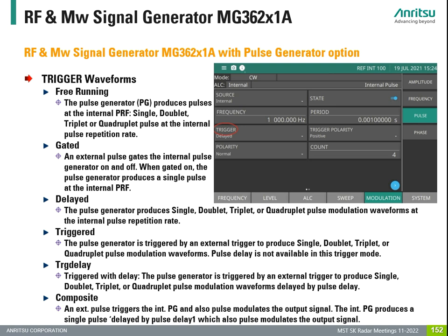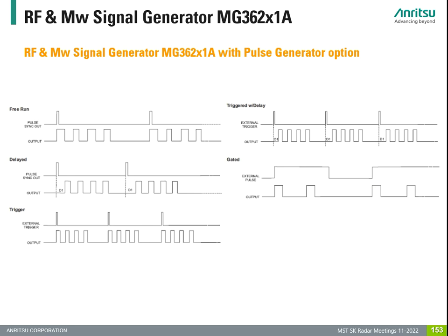For sure, it is possible to apply trigger to waveforms. Standard operations like free running trigger, but also gated, a delayed or an external or internal trigger, or even a composite trigger is possible here. This final sketch explains the various trigger possibilities and the understanding thereof. Look to this a little bit later in detail if you want.